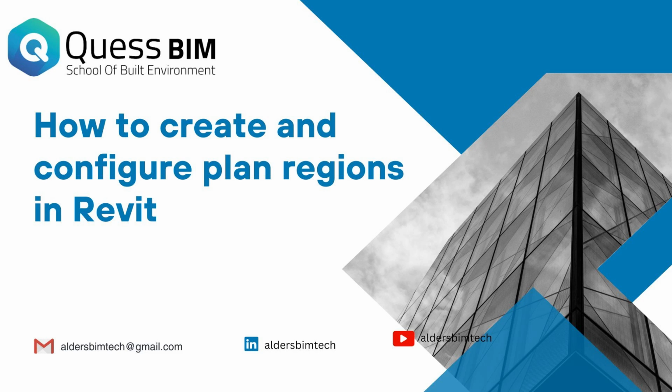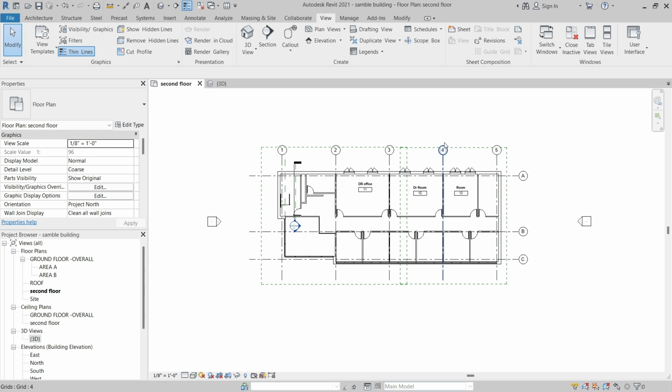In this video, you'll learn how to create a plan region in order to have a specific area with a different view range than the rest of the view. A common scenario for which plan regions are used is windows at varying elevations.